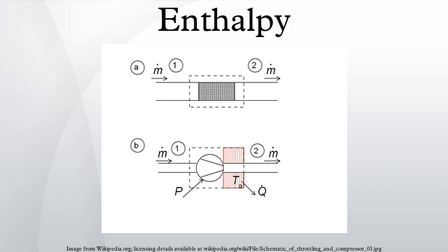Enthalpies for chemical substances at constant pressure assume standard state, most commonly 1 bar pressure. Standard state does not, strictly speaking, specify a temperature, but expressions for enthalpy generally reference the standard heat of formation at 25 degrees Celsius. Enthalpy of ideal gases and incompressible solids and liquids does not depend on pressure, unlike entropy and Gibbs energy. Real materials at common temperatures and pressures usually closely approximate this behavior, which greatly simplifies enthalpy calculation and use in practical designs and analyses.